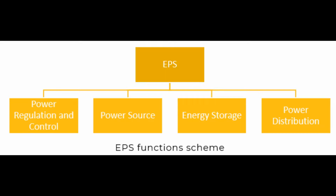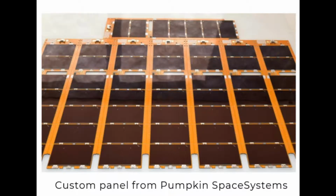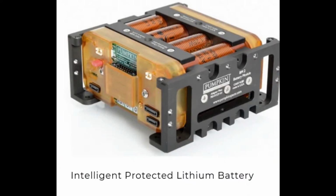The electrical power system, or EPS, provides, stores, and distributes electrical power to all subsystems. To regulate and control all the EPS subsystems, we chose the NanoPower P60. We need a gallium arsenide solar array that can provide 70 watts during daylight for the entire orbit. We chose the custom panel from Pumpkin Space Systems. Each cell provides 1 watt, so to get the 70 watts we need 72 cells to maintain symmetry. We need a lithium-ion battery that can store up to 93.42 watt-hour. The intelligent protected lithium battery from Pumpkin Space Systems is a good option for our project because it can store up to 100 watt-hour.